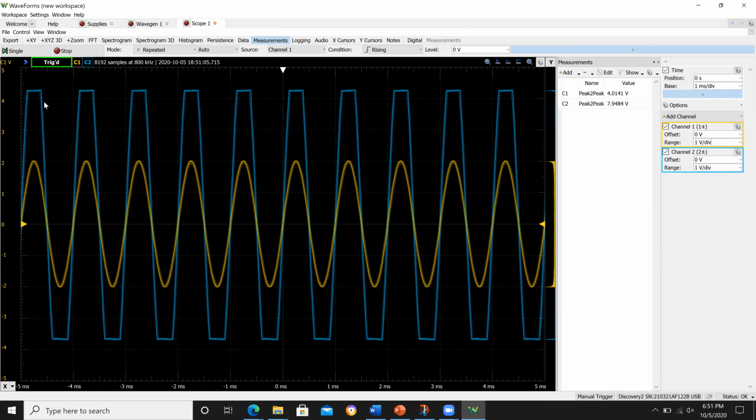And it appears to be asymmetric because this one goes over 4 volts, but this one doesn't even reach negative 4 volts. So why is that? Well, that's why you go back and you look at your data sheet. Your data sheet's going to tell you that your op amp is only capable of reaching within a given voltage or fraction of the supply. And I say fraction because if you scaled this up to 10 volts, this would probably scale up by that fraction, possibly, and be within, you know, that percentage of the 10 volt.